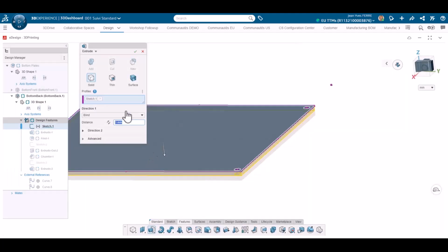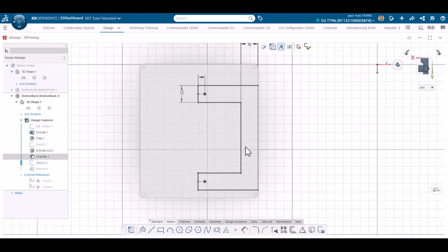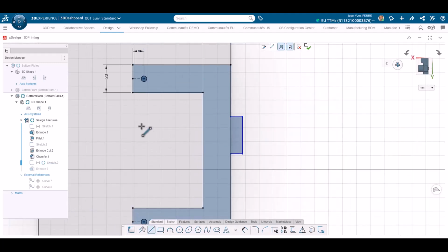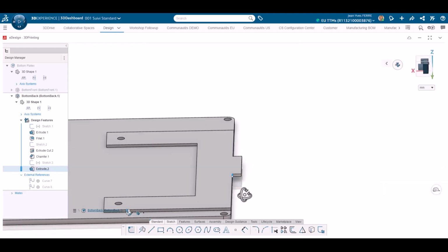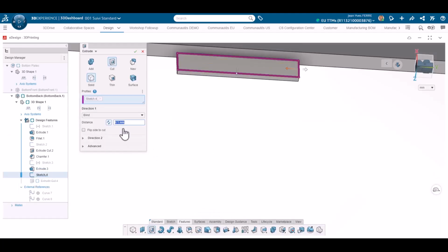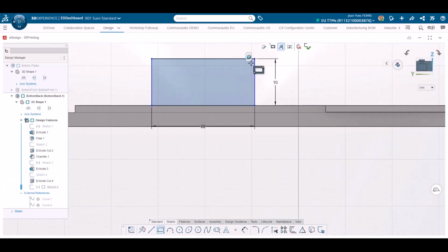It makes sense. I center the rectangles from the holes with the usual trick, aligning vertically on middle points, and I create the boss. And a little more thickness, by the way. Then I create a lip that will increase contact surface with the other part and help centering them together. I add a couple of dimensions to position the lip properly and some clearance for correct fitting. Yes, I can learn from my mistakes, sometimes.